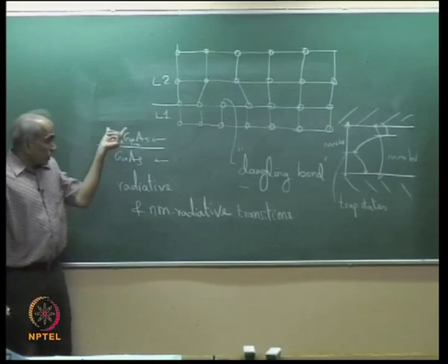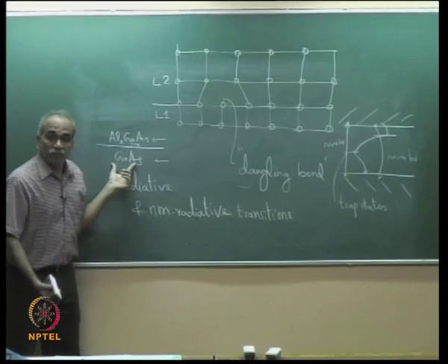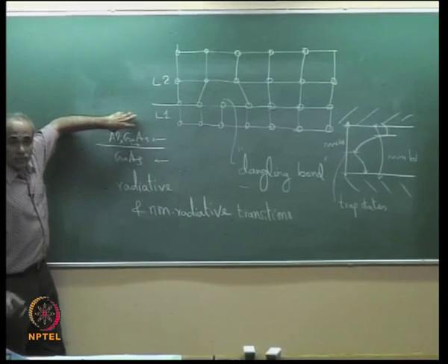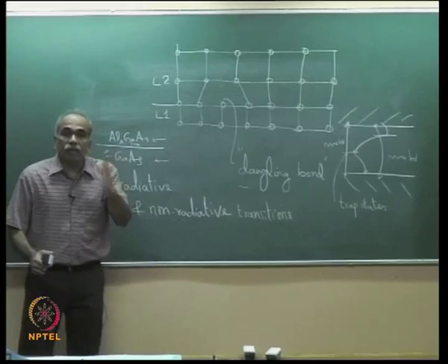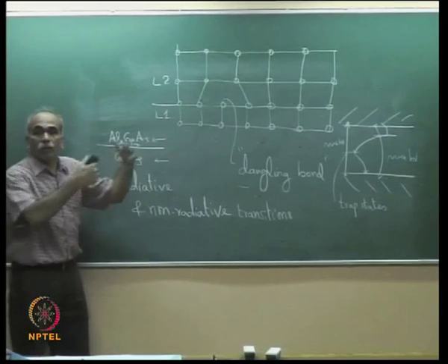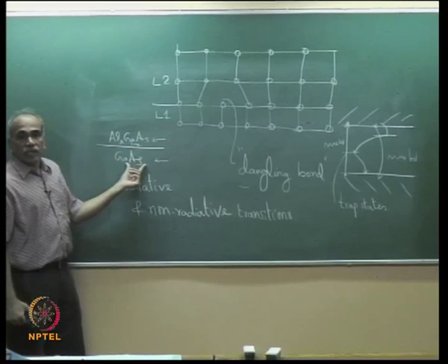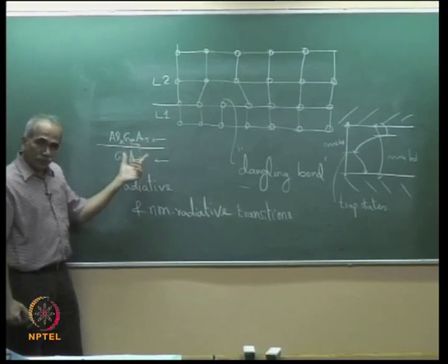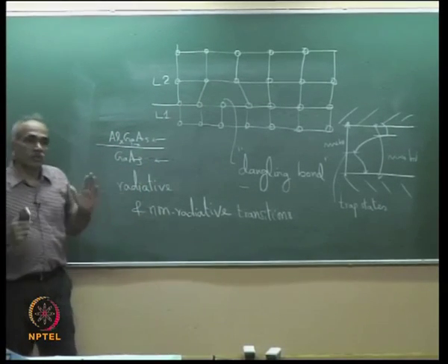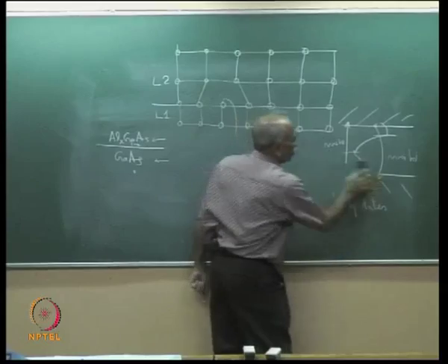In other words, what kind of materials can we grow on a given substrate? Maybe gallium arsenide, maybe indium phosphide. What are the materials which we can grow? We want materials with different band gaps because we would like different emission wavelengths. So, we would require materials with different band gap for our application. But when we take materials of different band gap, what is the substrate that we should choose, or what is the composition that we should choose, and is there lattice matching or not? This is the concern when you talk of lattice matched growth of layers.